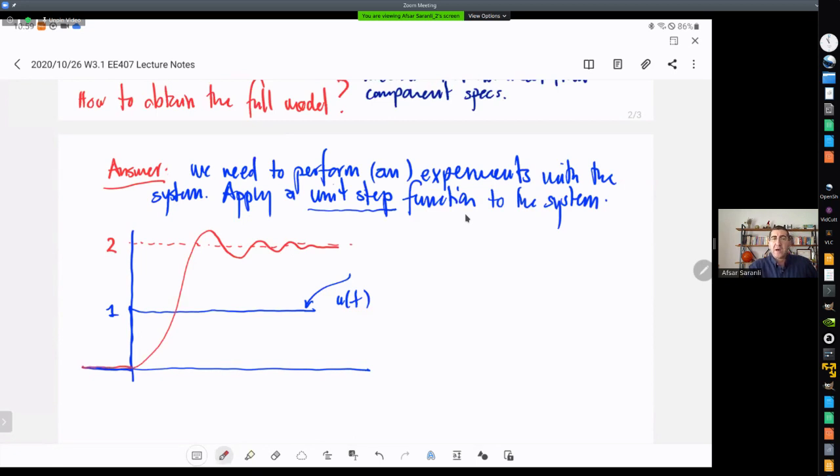Okay. For second order systems, we have a pretty good understanding of how model parameters are reflected into the actual response. So this system identification does not need to be iterative, or need multiple experiments and optimization and stuff like that, because we have a good understanding of how model parameters correspond to the actual response.